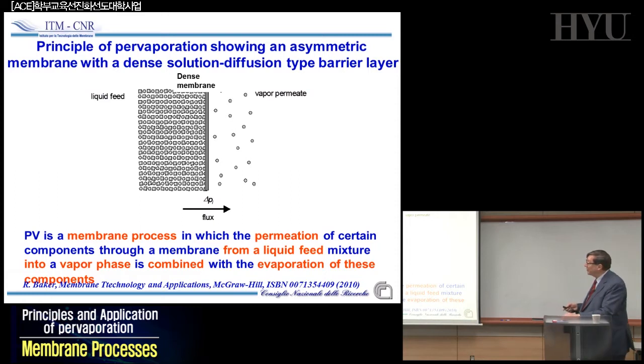It's important to understand this, because if you make a mistake when working with flat sheet membranes and use the dense skin side instead of the porous support side, you kill your process. Not for the membrane itself, but because you induce much more concentration polarization and thermal polarization phenomena, which basically destroy the operation.